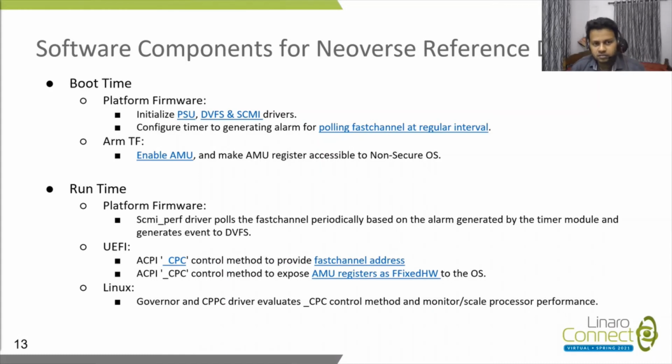And the runtime part, on the runtime, the platform firmware SCMI driver should poll the fast channel periodically based on the alarm generated by the timer module, and based on that the SCMI perf module needs to generate events for the DVFS module. And on the UEFI part,